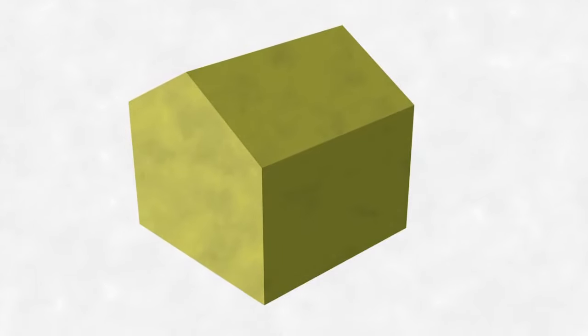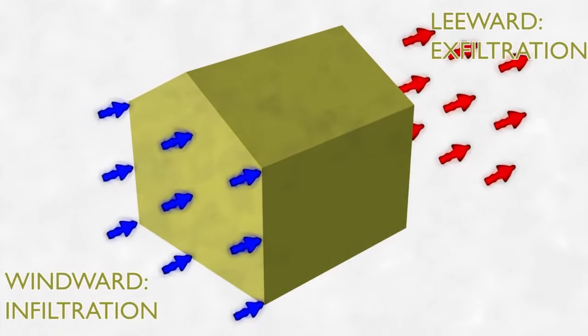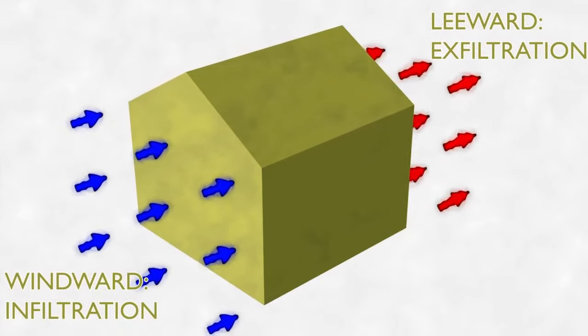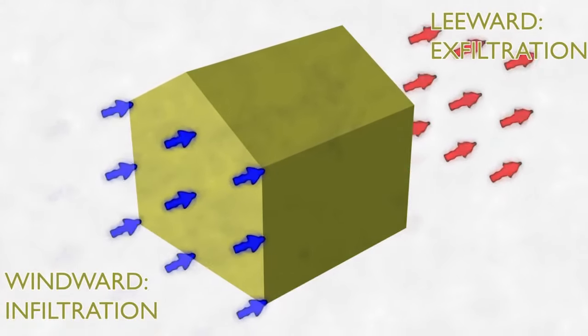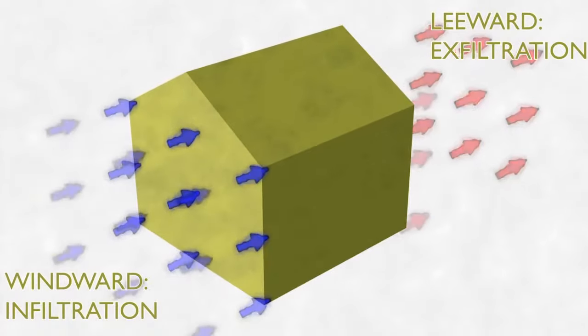Externally, the wind forces acting on the building will have similar effects, but instead of the pressure gradient working from bottom to top, it will be aligned to the wind direction. Cold air will be pushed in on the windward side where there's a positive pressure, and warm, moist air sucked out on the leeward side where the pressure is negative.